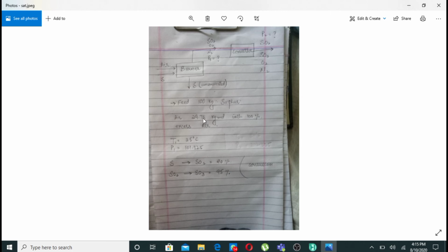If you apply the mole balance and find the degree of freedom, you will see that the degree of freedom comes out as 1, which is not equal to 0. So I back-calculated and found the air. It was given that 100% excess air was used. Firstly I found the required air from the balanced stoichiometric equations. Then I put it in the formula and calculated the excess air.